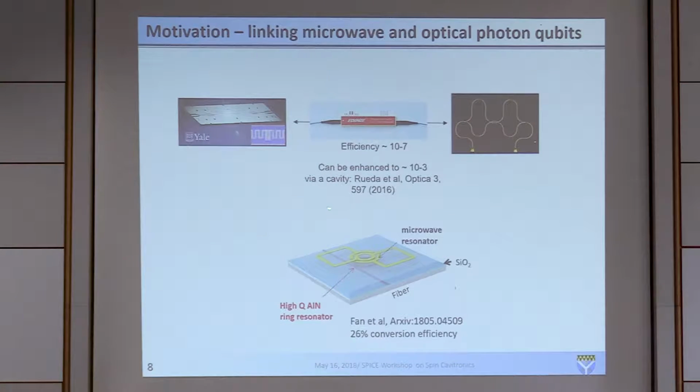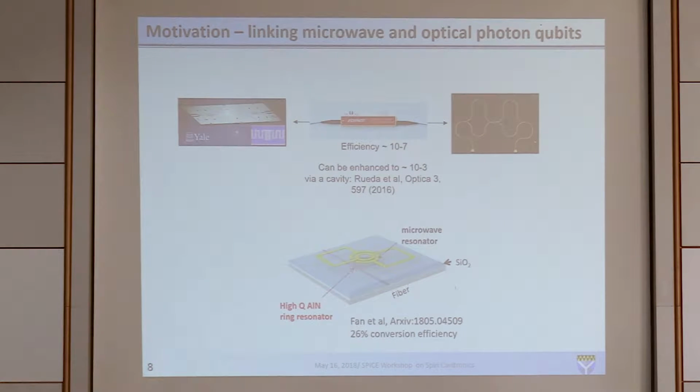So now, instead of patterning the lithium niobate into a disk, you make a little tiny ring resonator here. Then you put a microwave resonator on top. This looks like gold, but it's actually niobium nitride, which is a superconductor. And there's a reason we designed this superconductor to look like the symbol of infinity. It is a special resonator that allows us to phase match the microwave to the optics down there. So the microwave and optics can couple in the near field.